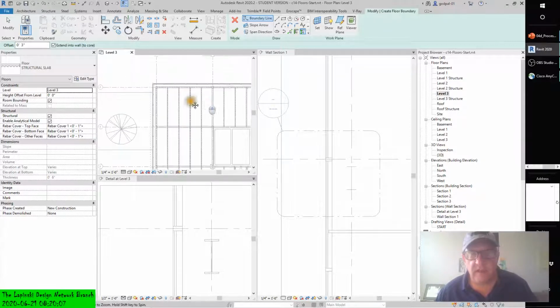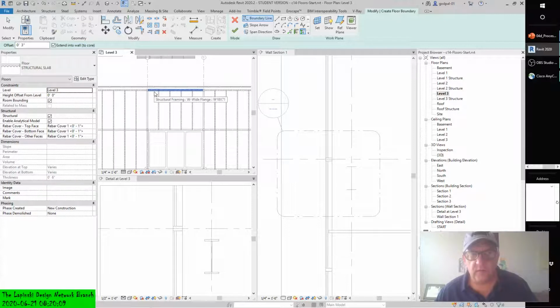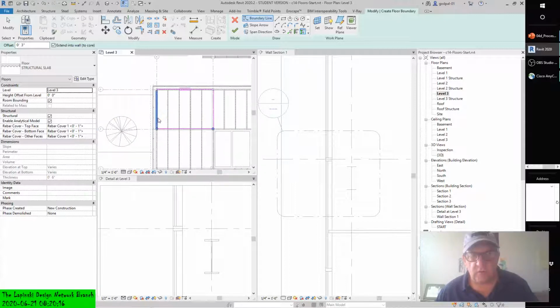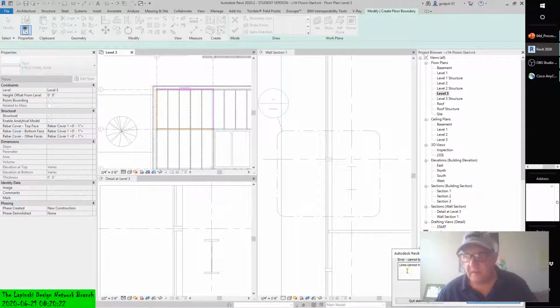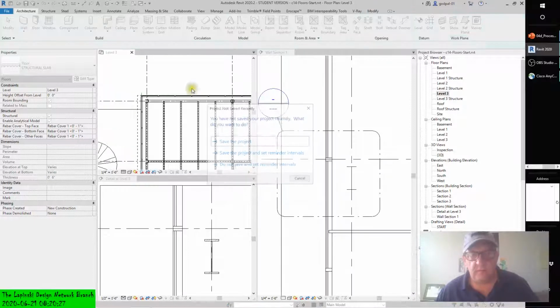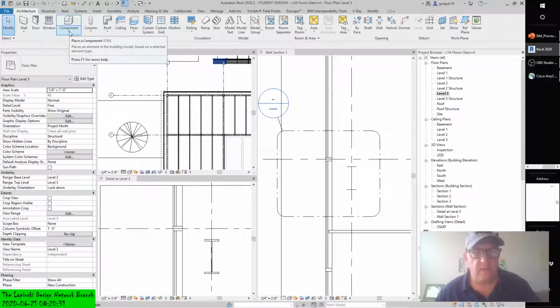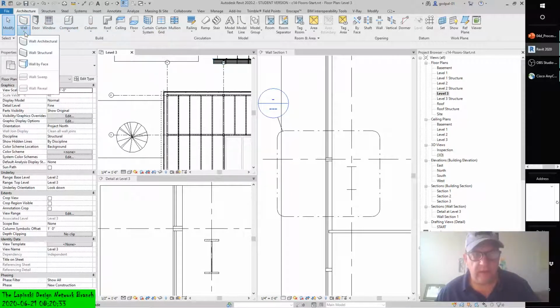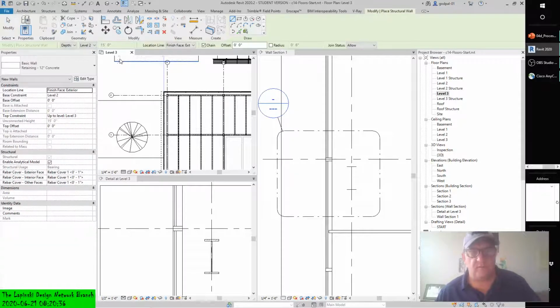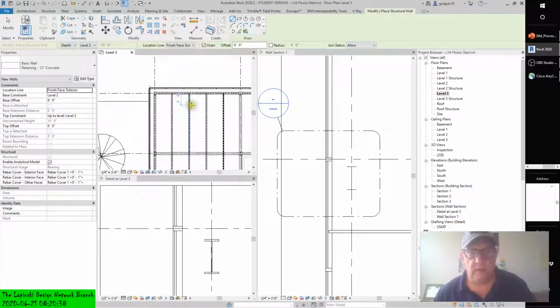grab this. And again, they're individuals, right? There's nothing saying I can't grab these and create a floor. Now the offset is going to cause an error. You'll see. Lines kind of intersect each other. Quit sketching, right? Because we have that offset set. It's a 3. And we can't have that yet. We can cantilever it. We can't have it offset from the core because then the lines are going to intersect.